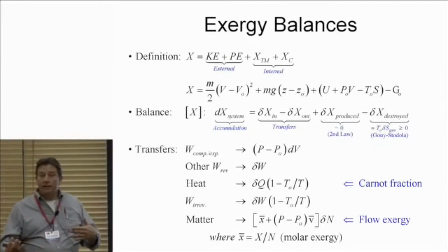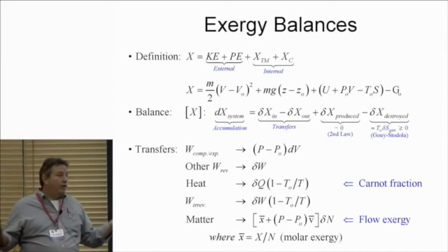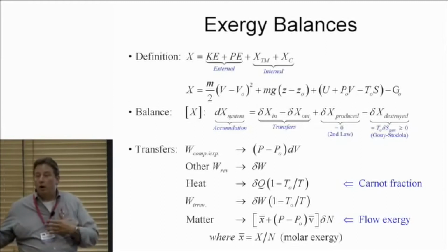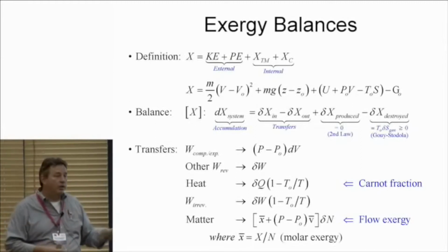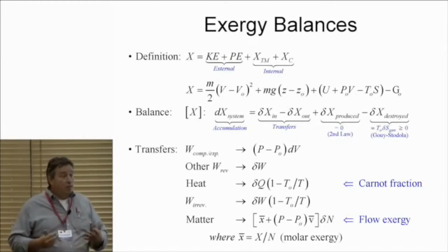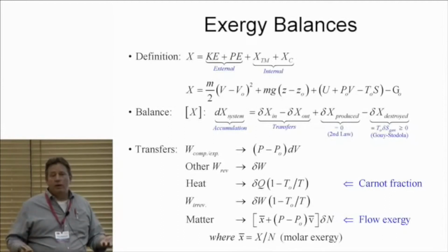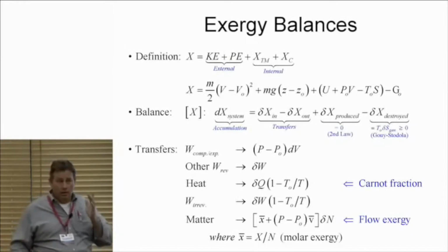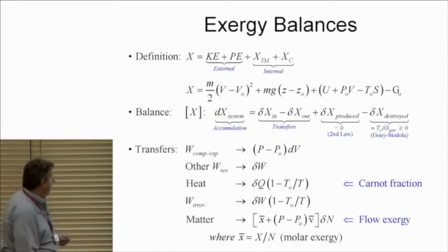If you're doing a chemically reactive system, which enthalpies of formation are going to be 0 at 25 degrees C? Are you going to honor the third law of thermo, the entropy goes to 0 when you go to 0 Kelvin? So by the time you put numbers in, you have to specify external references. So the idea that you have to specify an environmental state is not really a tricky one. If you accept that, then it's a property. And you function with it just like any other property, any other quantity. You write balances for it.